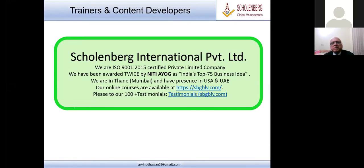Mr. Sheikh Aslam has asked, thanks for the seminar. Could you please explain how to calculate the input electrical power for chiller and corresponding pumps? Yes, you have a clamp meter, you know the voltage from the clamp meter, you know the amperes. There's a simple formula: for single phase it is V into I, and for three phase, the formula is square root of 3 multiplied by V into I multiplied by power factor. So it's very simple to calculate what power is being consumed.